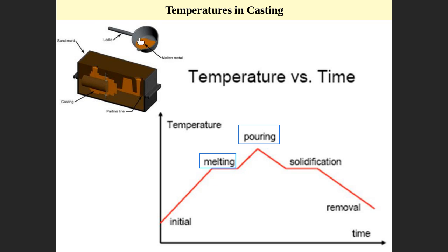If the liquid's temperature is the same as the melting temperature, once you put it inside, the temperature will drop, meaning solidification will start. Probably the material solidifies here and does not fill all the cavity. So to be sure that the material fills all the cavity perfectly, you have to increase the temperature up to the boiling temperature, probably 100 to 150 degrees Celsius above the melting temperature.